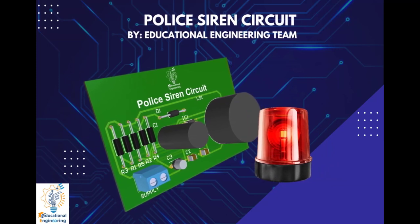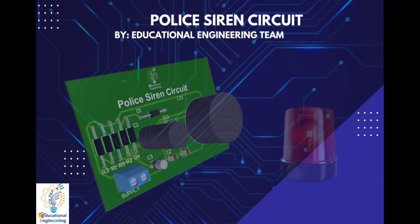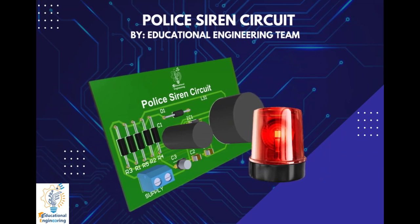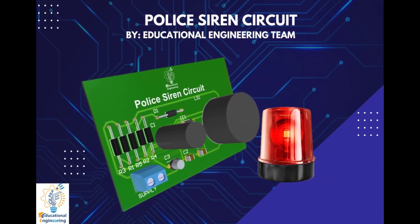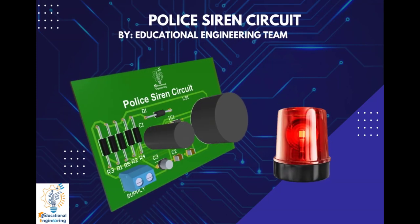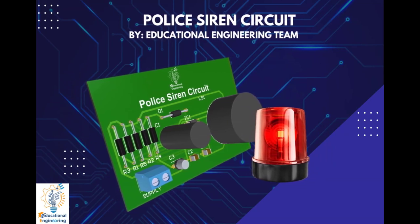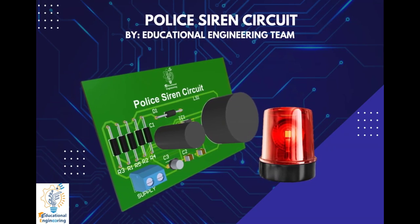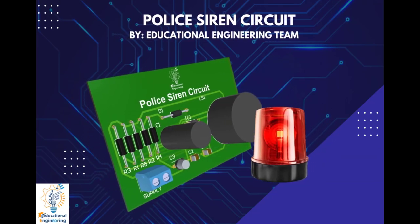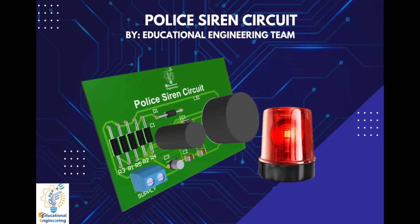In this circuit, the IC555 is wired as an astable multivibrator and it gives continuous square waves as an output. Since the output of the IC1 was given as a control voltage to the IC2, the output of IC2 will be modulated by it. Hence, this modulation action is responsible for the siren effect and the output can be fed into a speaker. Thus, it produces the siren sound. The circuit can be powered from anything between 6 to 15 DC volts, and by connecting this output to power amplifiers, we can further increase the loudness of this siren.